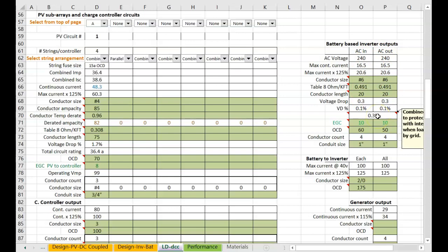This happens whenever you are in bimodal mode and it's in the evening hours, your batteries are full, and all the loads in the critical loads panel are being served by the grid. So it's going the full length of the connection from the grid connection into the inverter, and then from the inverter to the critical loads panel. So if these are a long ways away from each other, and I've seen this happen several times, then you have a pretty significant voltage drop. We don't here, we only have 0.3%, that's negligible.